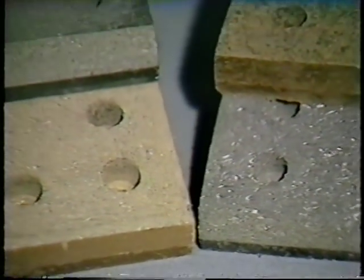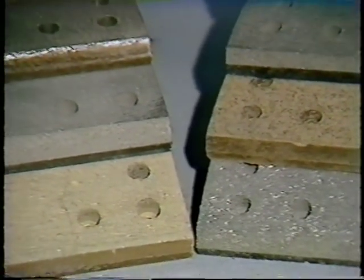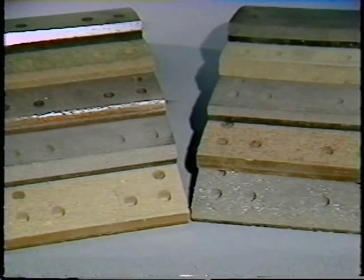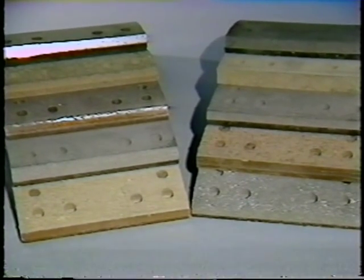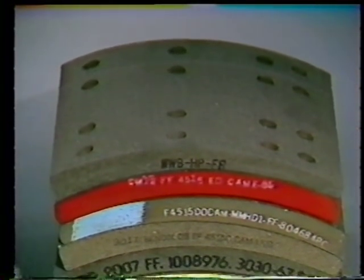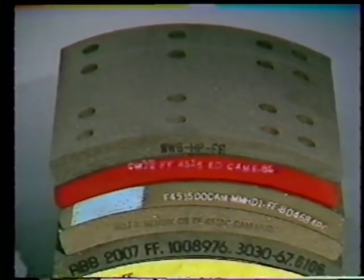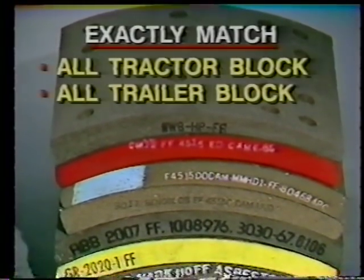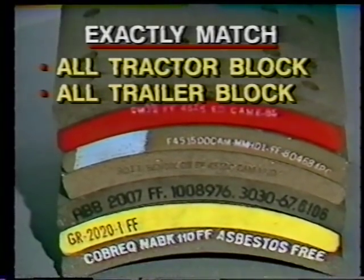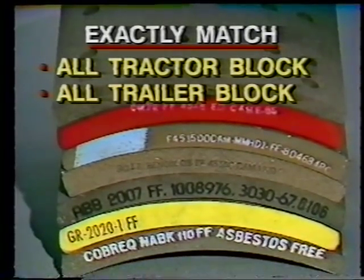A second factor that can affect mechanical balance is the block used. Each grade, brand, and edge code provides totally different braking capabilities over a range of operating temperatures. Even blocks with the same coefficient of friction on their edge codes can provide radically different levels of friction. So the exact same brand and block should be used on every wheel of a tractor or a trailer.